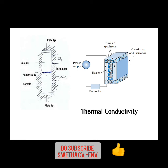In this method, a filament is electrically heated in a special apparatus to a temperature at which the gas or vapor becomes oxidized and burns at the surface of the filament. So at the filament, it is heated and the gases and vapors will be burnt, okay? Then the energy developed during oxidation, nothing but the combustion, is measured with a thermocouple. So how much energy is generated by the combustion will be measured by the thermocouple. This method is mostly used for determining carbon monoxide.